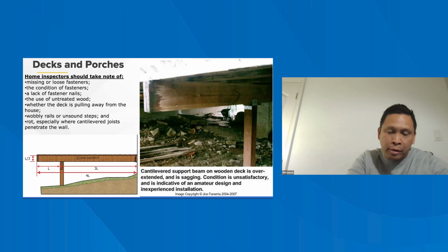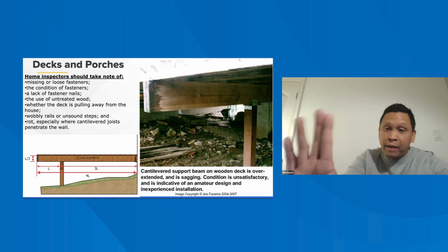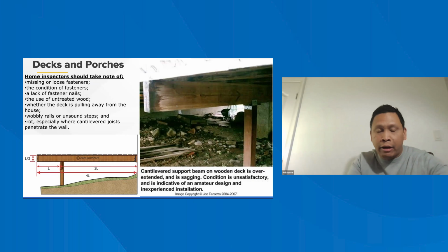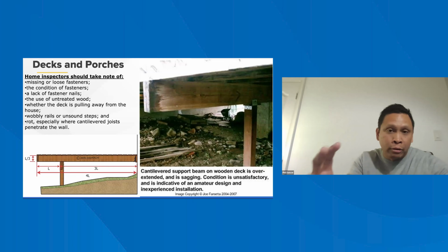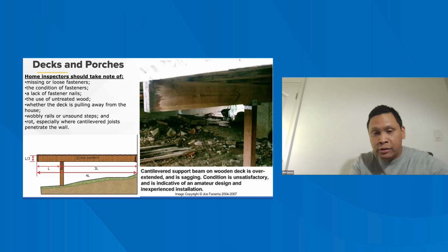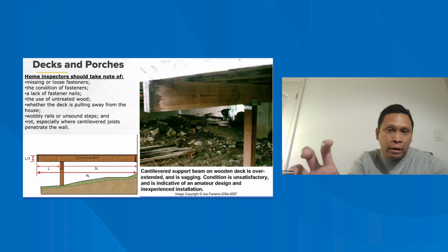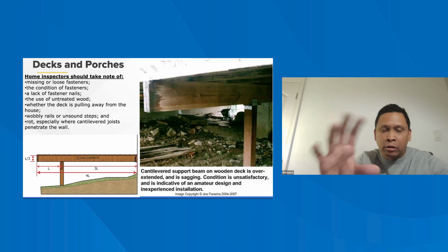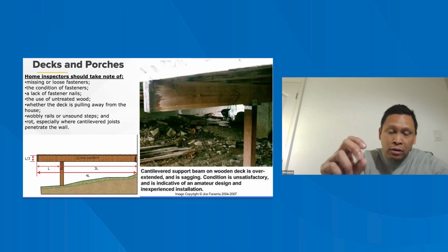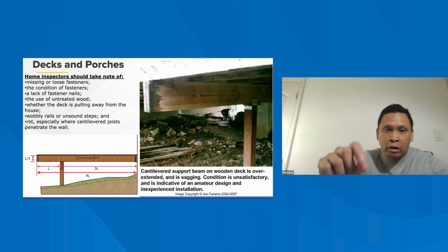I know we all come across this when we're looking at hangers. Not only do they have face nails, the left and right side of the face of the hanger, they also have shear nails. It's a diagonal nailing pattern that also helps to increase the strength of the overall system. But also remember, I said diagonal. The manufacturers, the more popular ones, MiTek or Simpson Strong-Tie, design these shear nail openings in such a way. Simpson Strong-Tie calls it a predetermined dimple pattern to be installed diagonally.